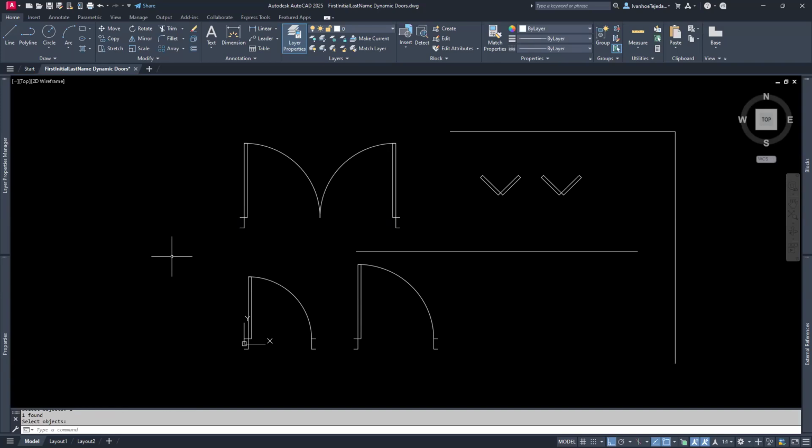So think of AutoCAD as keeping a list in inventory, and it remembers in what order everything was drawn. If I wanted to, I can keep doing this, L for last, and it would go back and erase every single object that I've drawn. Not that I ever want to do that, but AutoCAD is keeping track of these objects on your screen, and when you select them, create the selection set, P for previous, all of that.